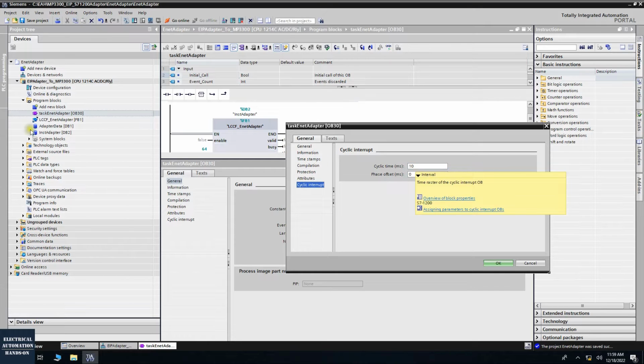After all, for this small PLC, this add-on function block is an add-on feature, right? If we set it too high, basically your controller will put a lot of effort on those communications rather than on its control task. Okay, so leave this 10 milliseconds here.